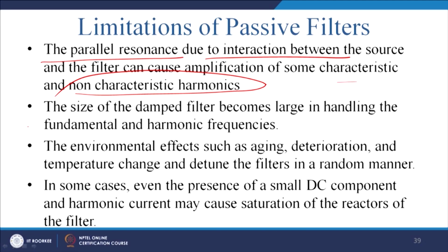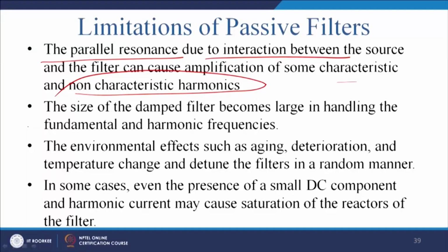So, since it offers anti-resonance, it will offer very high impedance to a particular frequency. That may disturb the power system, which was not at all an issue in a particular case, because it will aggravate because of this parallel resonance problem.